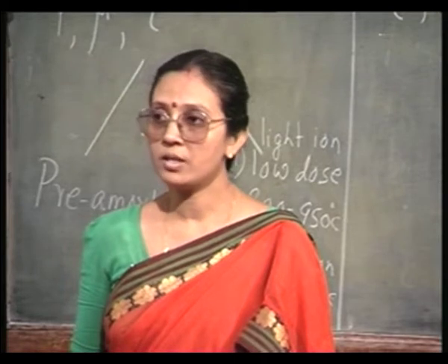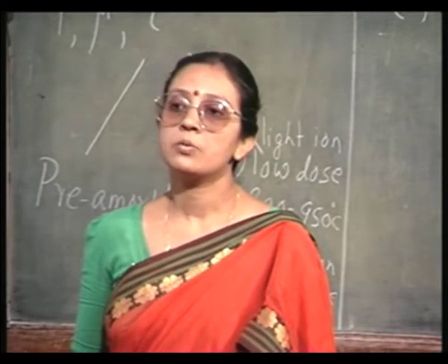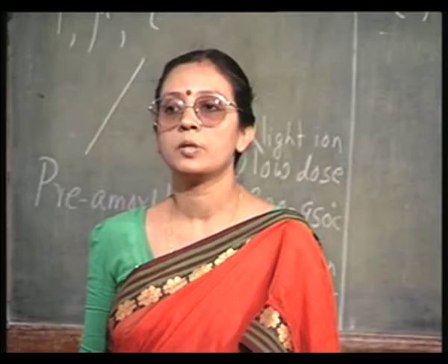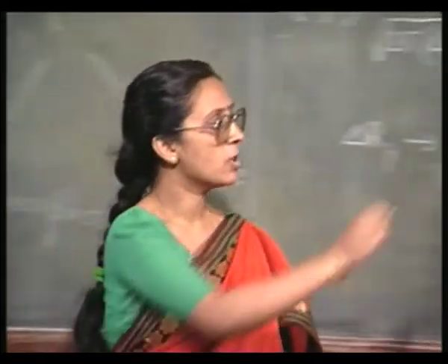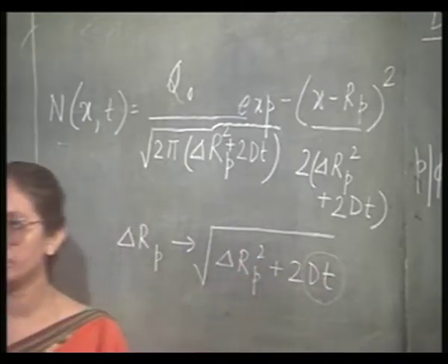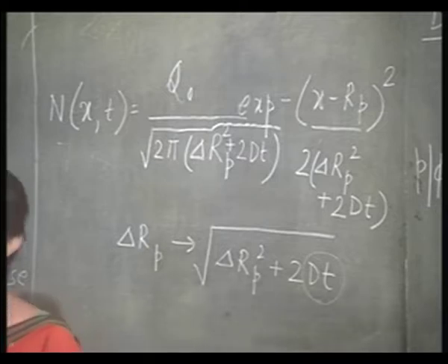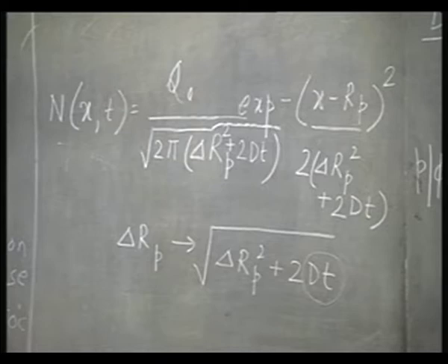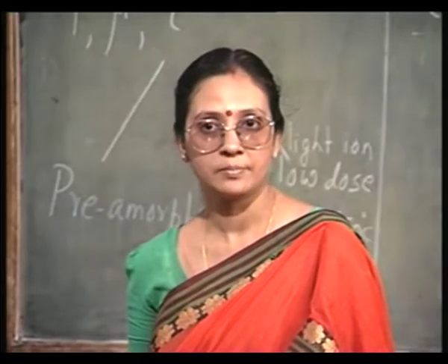The advantage is that there is absolutely no change in the doping profile. You see, you are keeping this t extremely small, so even when the temperature is large, the product Dt still remains very small. Therefore, the dopants do not have sufficient time to move inside.